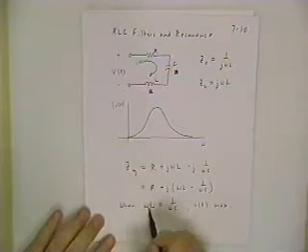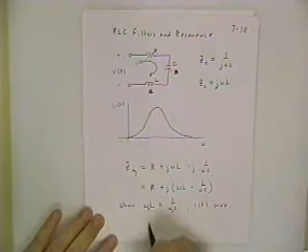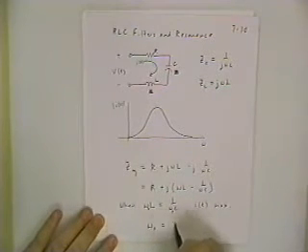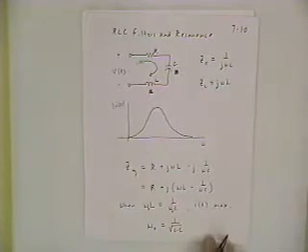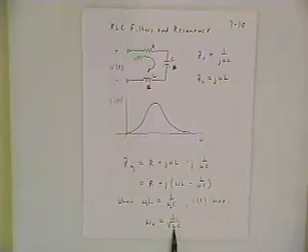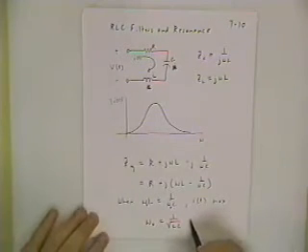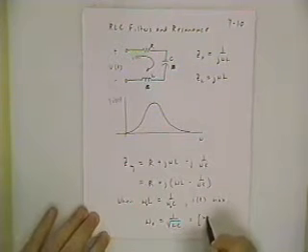And that happens at a special frequency called the resonant frequency. Omega naught is 1 over the square root of LC. Might be interesting to look at the units for inductance and capacitance and prove to yourself that this has units of radians per second like it's supposed to.